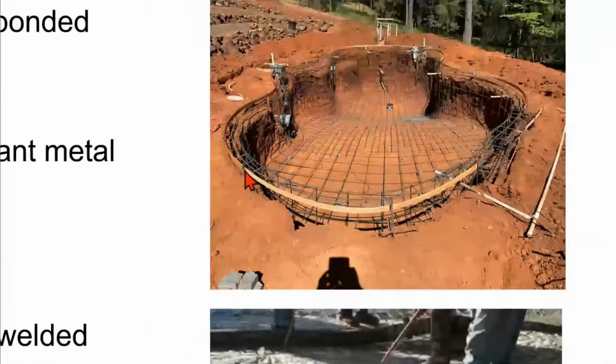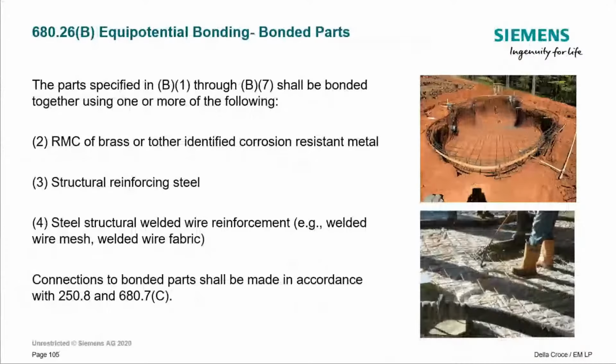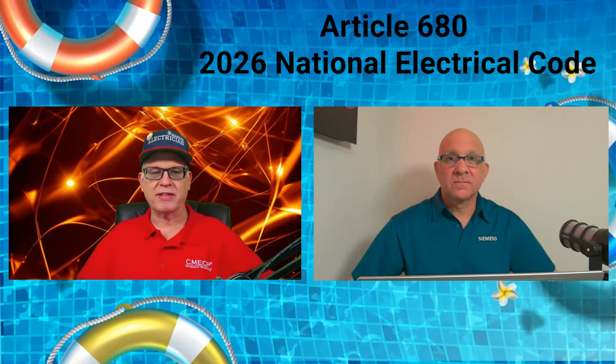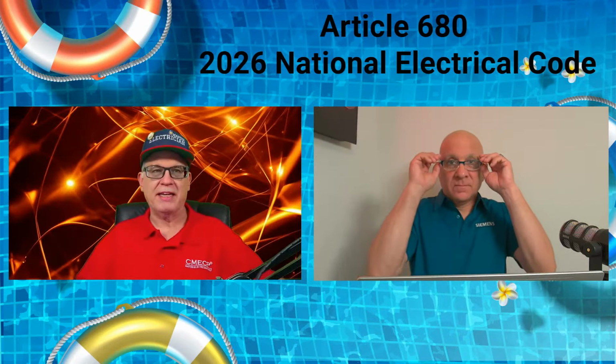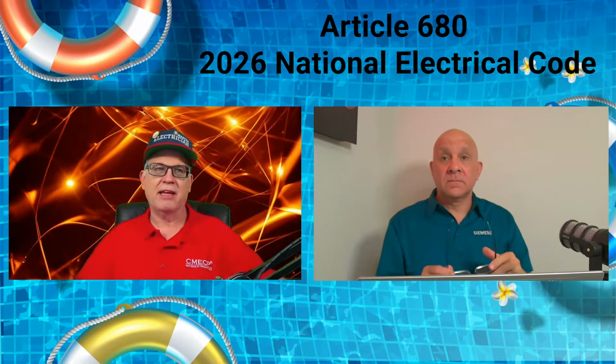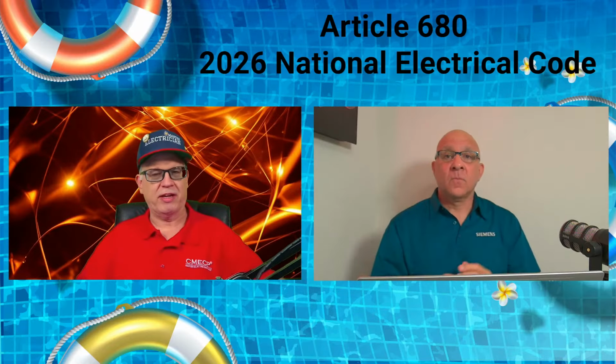Get that stuff inspected, man, let me tell you, do not not get it inspected and then come back later and ask the inspector, well, what can I do? The inspector is typically not going to look at you and go, oh, I'll just let you drive 4 ground rods around. That's not how it works. People call all the time and say, oops, I didn't do an equipotential bonding grid. Can I just get away with adding ground rods or something like that? It's not how it works.